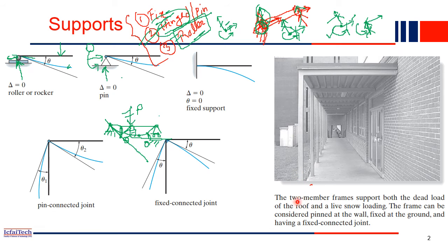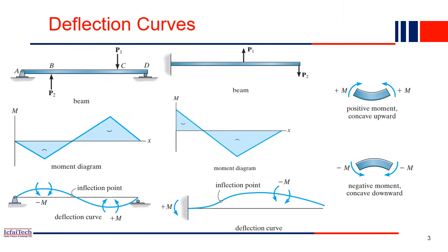This is fixed and grounded here, and this joint is basically a welded connection, right? So this is also a fixed connection. This joint is also welded, meaning a fixed connection is there, right? So that's how we make our original structure into analytical models. These are the analytical models, and we do our structural analysis.